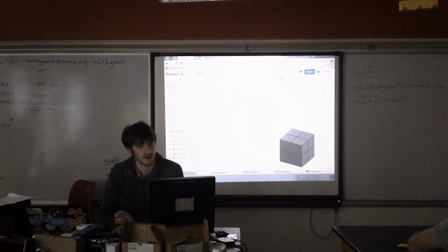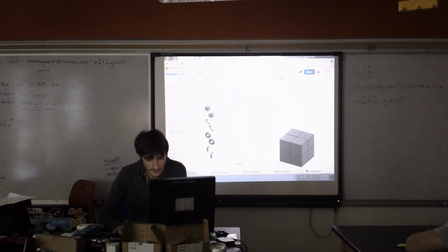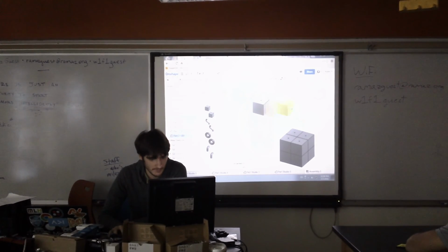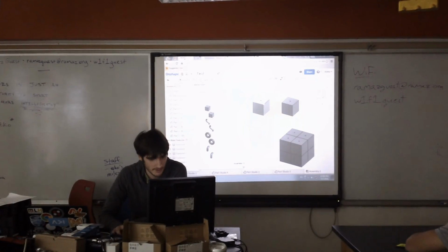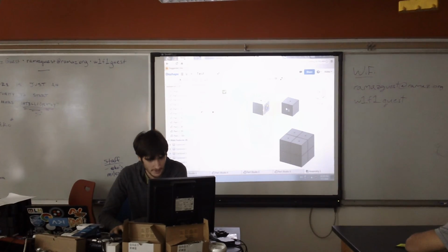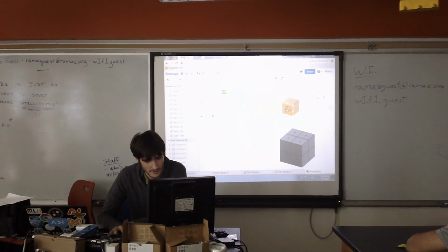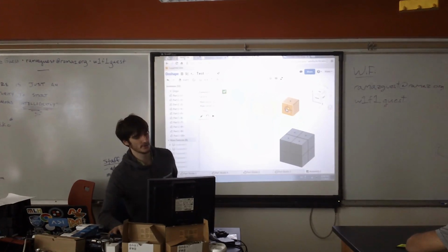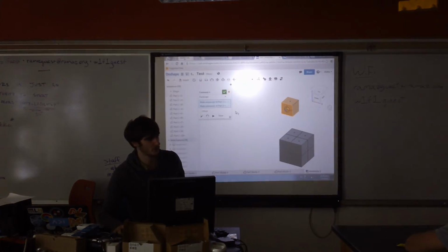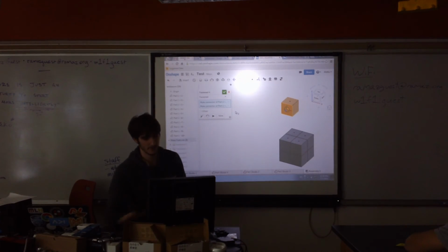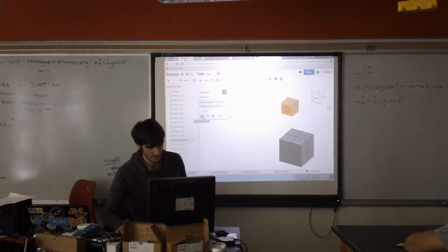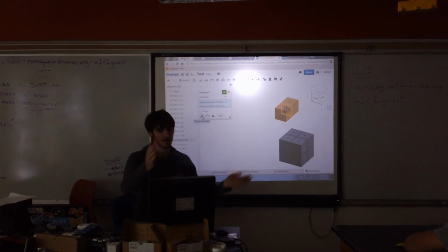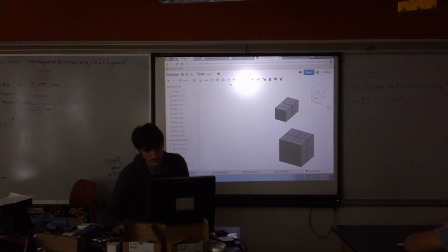So now you've made your parts, you've got to put them together. What you do is you just put your part in. You can put another part in. And then you tell it, I want to stick this one here. A lot of times, for whatever reason, the algorithm is weird and it always tries to put something inside of the other thing. All you have to do to fix that is flip the axis. And so now those two things are touching. And if you move them around, they stay touching.